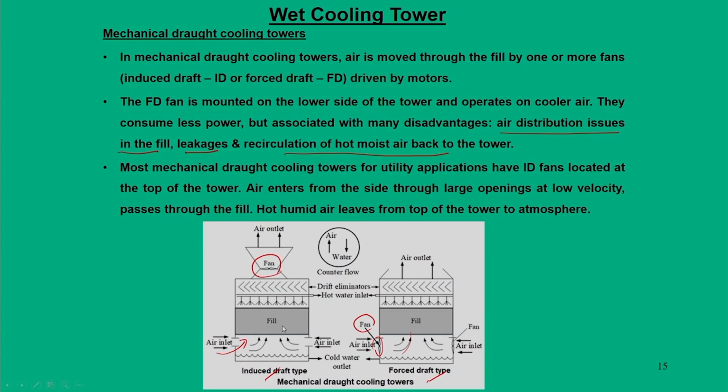Through this process, another advantage is that mixing of water with air is very much possible in this fill or packing. That is the most important advantage of an induced draft type tower. Second, the issue of back pressure does not arise. So, because of this advantage, most of the wet cooling towers are normally induced draft type, of course if it is a mechanical draught cooling tower.